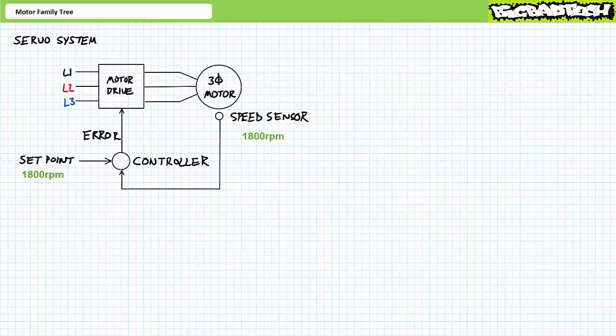Yes, there is a motor in this system, and yes, people do refer to these motors as servo motors, but they are technically not correct because there is no such thing as a servo motor in isolation, but rather a motor must be part of a larger servo system, which includes an actuator, which may be a motor, a controller, and a sensor and a feedback loop to make it all work as it should. This is, of course, neglecting sensorless vector control, which, as they say, is another barrel of rage-infected monkeys, which we'll crack open at a much, much later date and time.